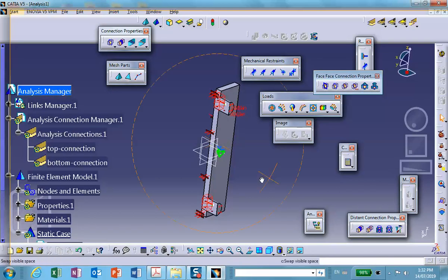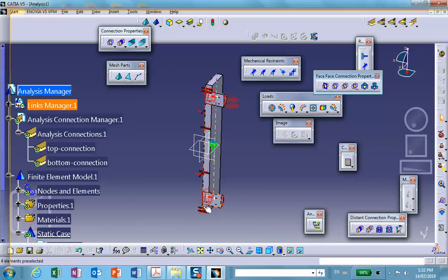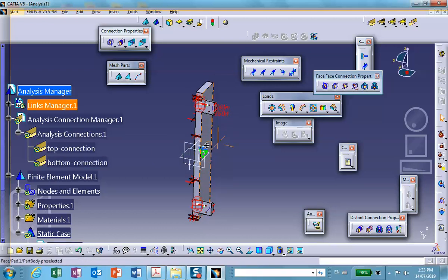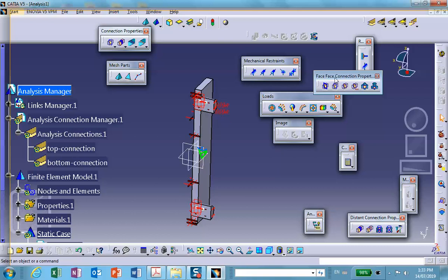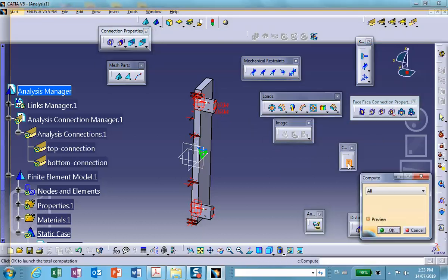Now, when we did this thing last time, a whole bunch of things happened. There was lateral movement of the top pin, lateral movement of the block, and lateral movement in the direction Y of the pin and the block. Now, these things will not happen when we use symmetry because of the surface slider constraints that we have. In fact, using surface slider makes you get to a final answer quite faster.